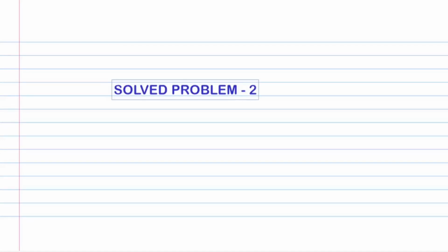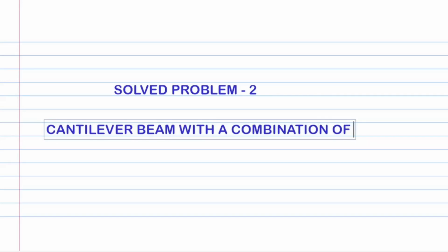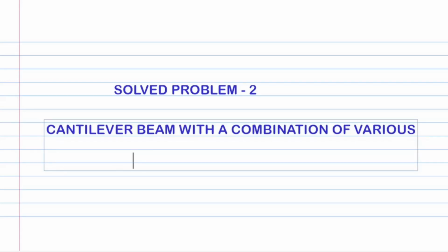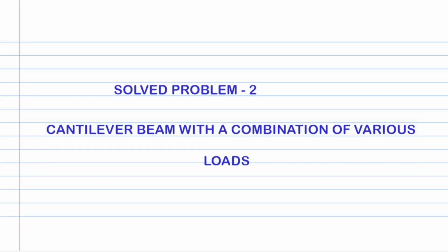In this lecture, we shall consider solving a cantilever beam with a combination of various loads for shear force and bending moment set up in a section along its length. Let's have a cantilever beam AB of length 5 meters with end A fixed and end B free.